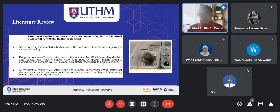Firstly, it will save time. The water cooled solidification of the bar was 5.8 times faster compared to air natural cooling. The second point is improvement. Based on the research paper, it was stated that SDAS, which stands for secondary dendrite arm spacing, and eutectic silicon were both improved greatly due to this technique. The tensile strength, elongation, and hardness were all enhanced dramatically compared to normal cooling.